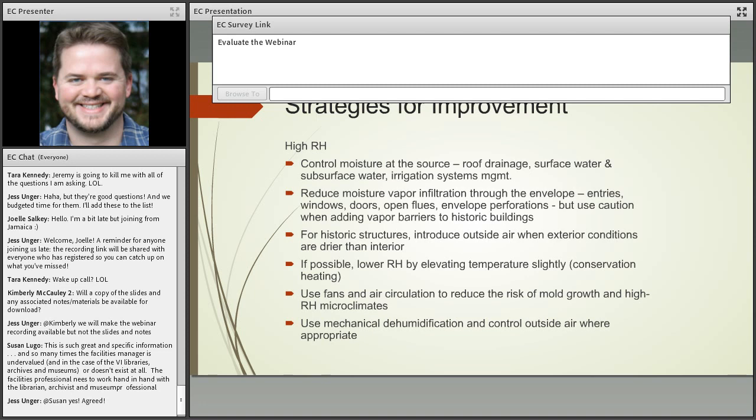And the problem with that is really there are a few problems with it. From an historic envelope perspective, that can cause a lot of problems. Positive pressurization in historic buildings is a root cause, and not the only root cause, but a root cause of a lot of the envelope issues that we have in historic structures. Because as we pressurize the interior of that historic space, we are forcing those temperatures, whether warmer or cooler, as well as that vapor, whether it's drier or wetter, depending on the season and depending on the operation, we are forcing that harder out through the envelope.